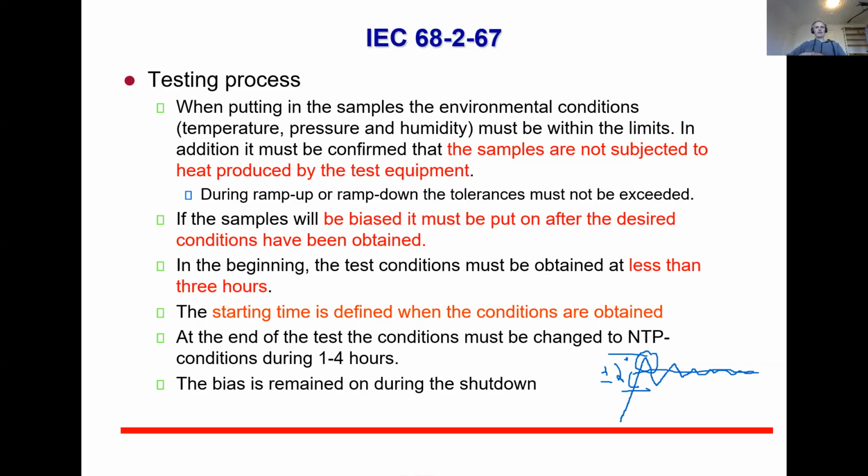I did some grinding and polishing. My sample was a power resistor that was porous, and I know that water went into the structure. Then I put that into the vacuum in order to remove the moisture, because I cannot put moisture in my scanning electron microscope, as there it's very high vacuum inside.